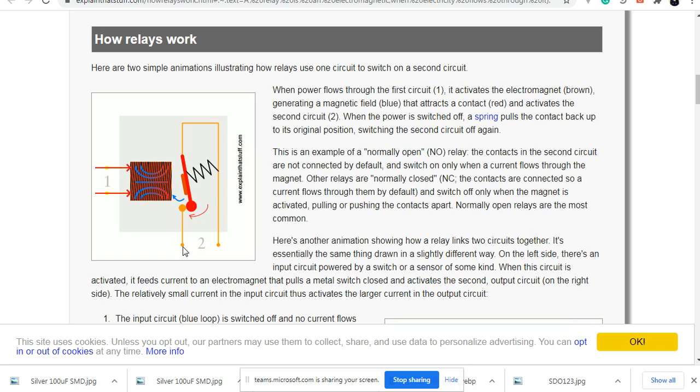So this means that the same thing which you do with a mechanical switch, a piano switch at your homes, is being done by a DC signal given to your relay coil. So the relay has an electromagnetic coil, and that coil has the capability of attracting a fulcrum towards one contact point. Now based on this diagram, you can easily understand that this is the common point, which means this relay is always connected with the live wire.